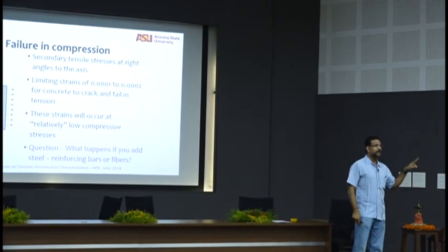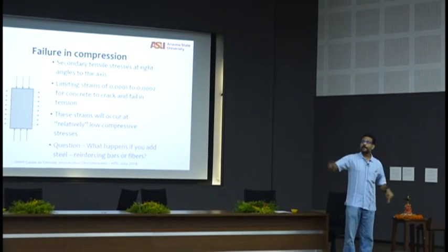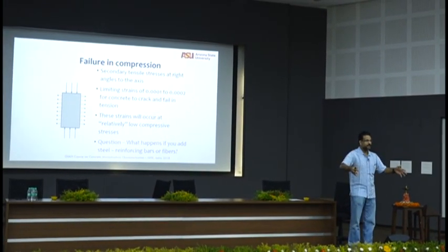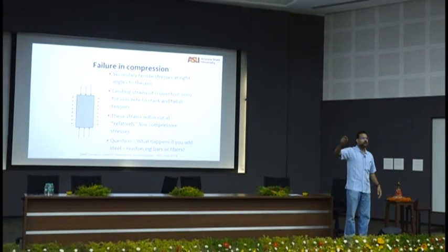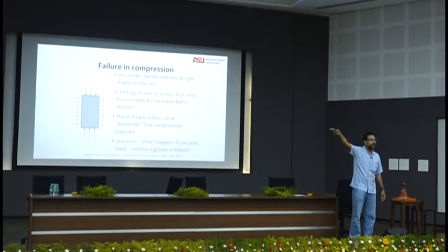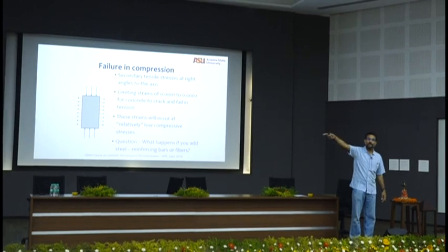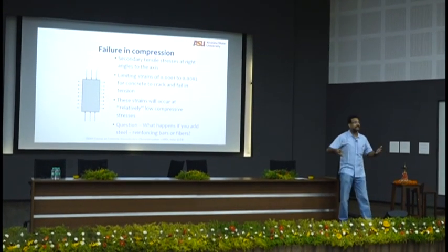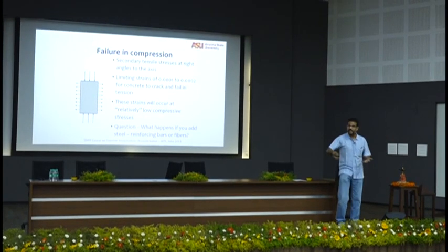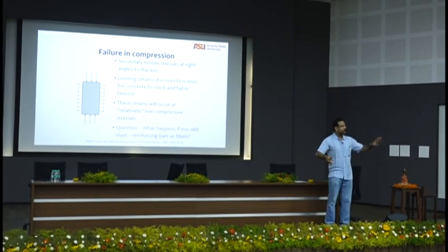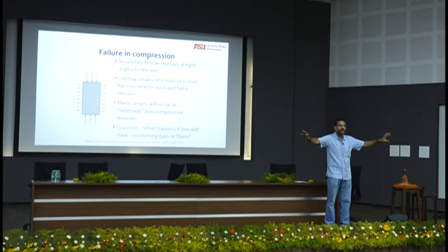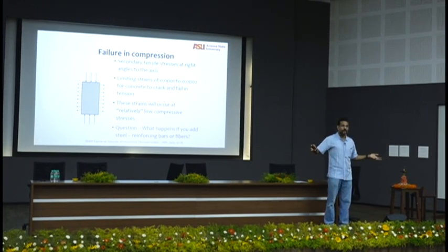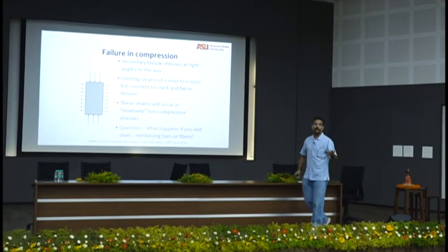One more reason why compressive strength is a bogus quantity. Because in real life, when failure in a column happens, you can go and core another sound portion of the column and you can still prove that that part is very strong. Whereas locally it would have failed. A bridge deck would have failed locally. You can go core at the extreme ends where it did not fail, it will still meet the compressive strength. Is it good enough? Failure is a local phenomenon, and